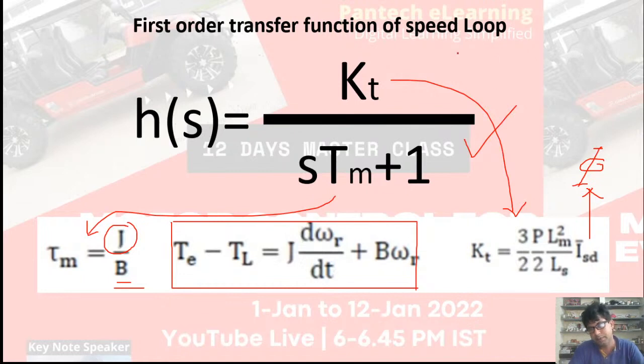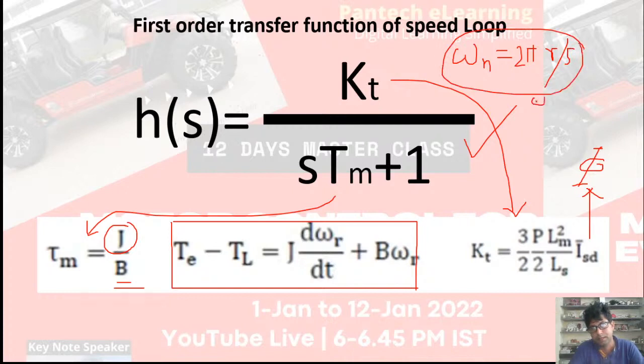And this loop natural frequency is 1 Hertz. Okay, so this is this much radian per second. And my zeta is equal to 1. So by substituting all these things, you can find out the K and T. Okay, I'll be showing you, don't worry, but through MATLAB, not by calculation. So these are all about the 3 reduced first order transfer functions of these 3 loops.